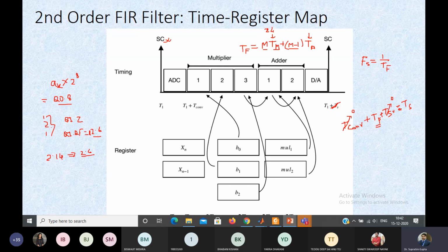So once you get that 2.6 format, now at the input of this DAC, what you have to do is convert this 2.6 format into 0.8 format. How can you do that? We have already explained it by that process, so that process should be invoked. It is the multiplication, so that means you add some zeros, then you divide it by the V reference. So you need to know the V reference in 2.6 format.